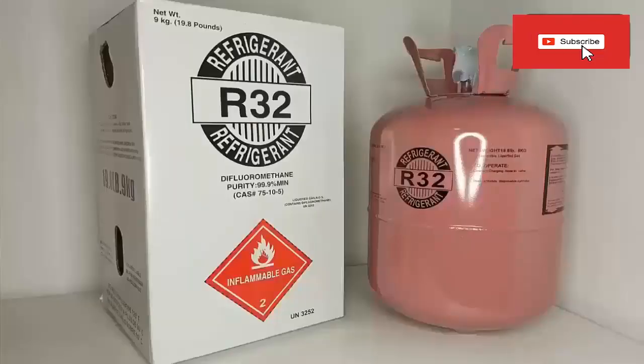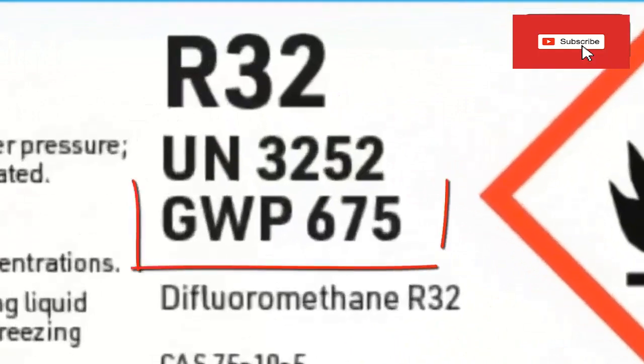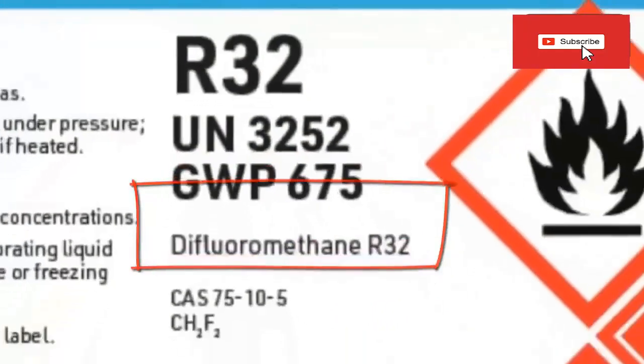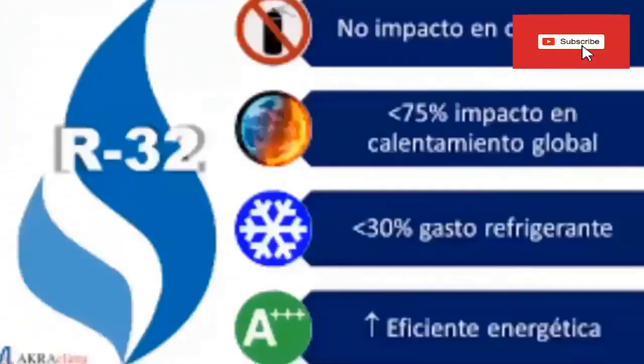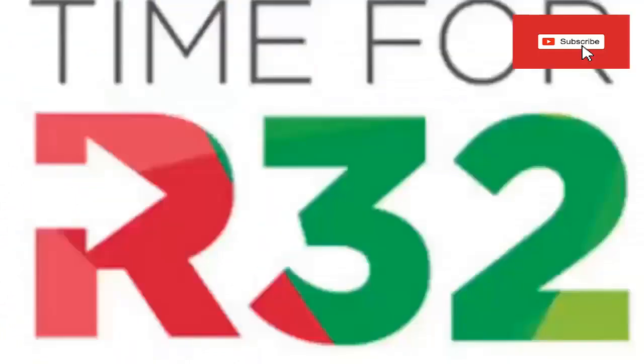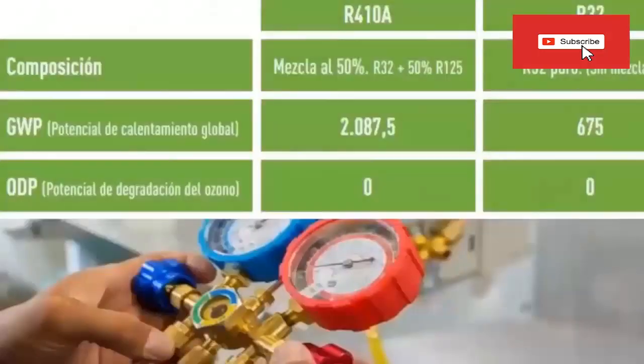R32 is a pure HFC type refrigerant, with a low global warming potential index, high efficiency and refrigeration power, which has made it the refrigerant of choice for many manufacturers for their new equipment. Now let's study in detail the characteristics of the refrigerant R32.